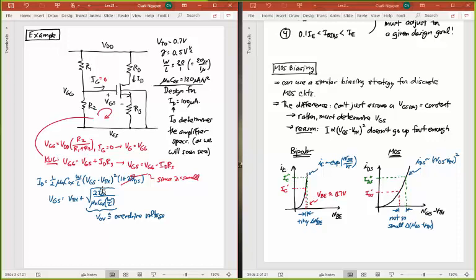The reason why is that's the extra voltage that you're putting on. You don't need to put that much voltage there, but that's the extra voltage you need to not only get that channel, but also to get a certain current flowing through that transistor, since you see ID is in this equation right here.